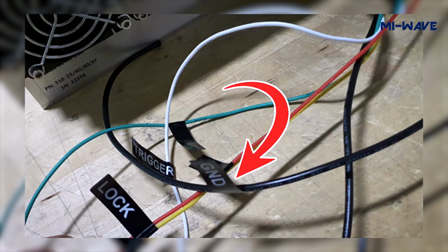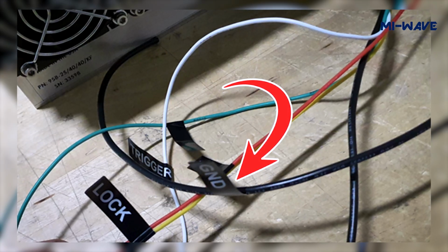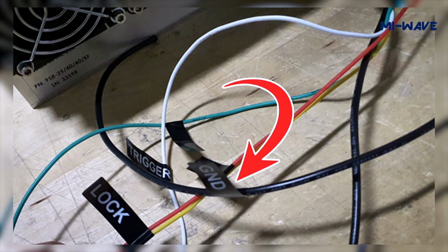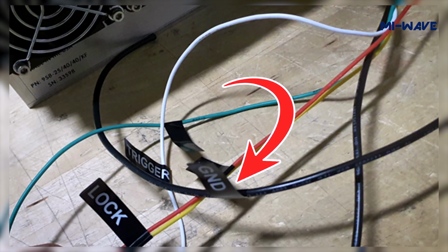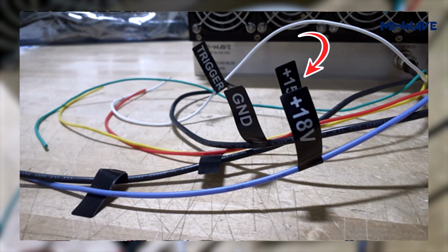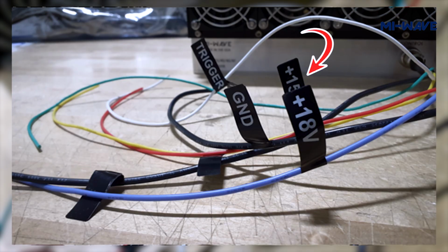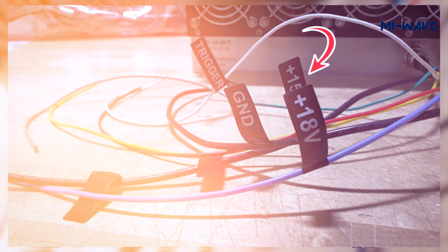Now let us look at how to operate the synthesizer. We will begin with mechanical connections. First, connect the wire labeled ground from the synthesizer to the negative or ground terminal of the 15 volts power supply. Next, connect the wire labeled plus 15 volts from the synthesizer to the positive output terminal of the 15 volts power supply. The 15 volts power supply provides power to the synthesizer unit.